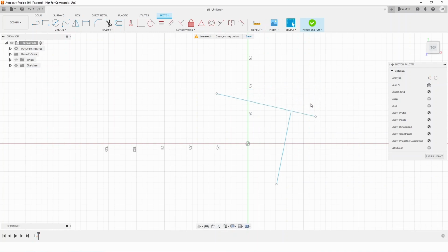If you haven't been paying attention, you might have seen other little blue symbols as well showing up while I'm moving this line. I'm actually gonna delete these by selecting them with the left mouse button, pressing delete and delete. So if I just create a straight line here, you can see a little symbol representing a horizontal constraint. It means our line will always be perfectly straight horizontally.